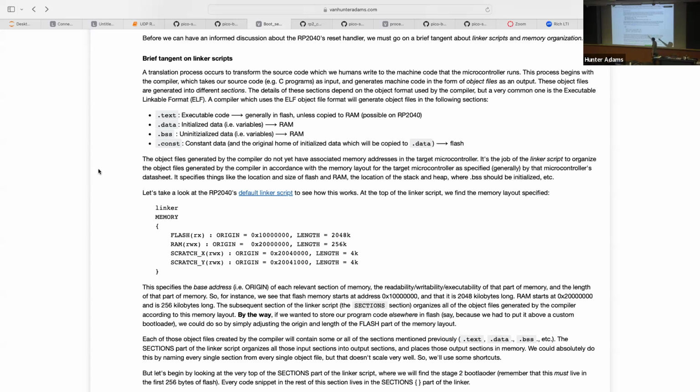And there's also a const section. I have mentioned in previous lectures that if you have, let's say, some big audio file, background music for your video game, that you want to have a DMA channel constantly be putting out, if you know that you aren't going to be modifying that audio file at runtime, it's a good idea to label that big character array that represents the background music as const. And what that tells the compiler is, my application code is not going to modify this at runtime, and so you are free to put this into flash memory as opposed to putting it into RAM. And so there's a section of compiler output stuff here called const that goes into flash memory.